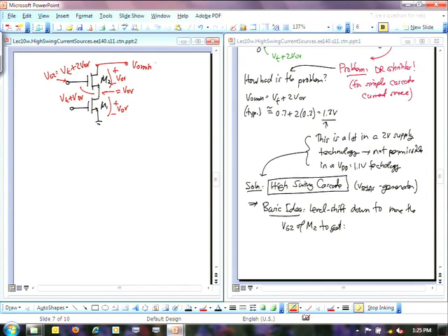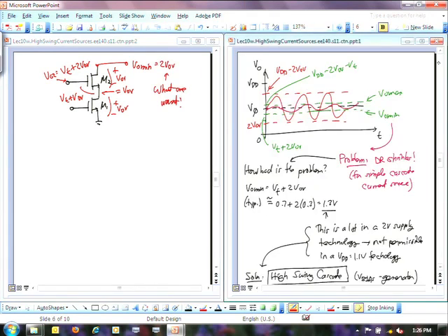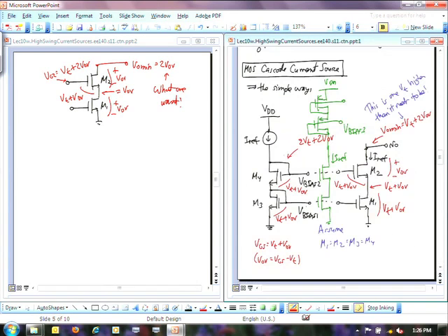Okay? So the trick is to change this circuit that we have before. So here's the circuit before, right? This was too simple here because if I put 2 diode connected transistors right there, then that voltage here becomes 2 VT plus 2 VOV. Right? That's 1 VT more than I need. And so if I could somehow create a bias voltage at this node that's equal to VT plus 2 VOV, then I've got my maximum swing out of this cascode. Okay, and it all takes a level shift here. It all takes a circuit that looks like this.